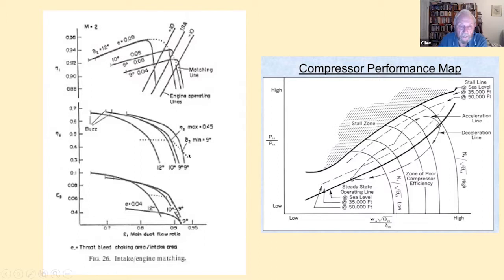But you do get then, as you run along the law we chose, which is that we would run at a constant ramp angle for a while and then run at a constant bleed pressure, as you do that, you find that the bleed from the intake varies, and then at constant bleed pressure it holds more or less constant.